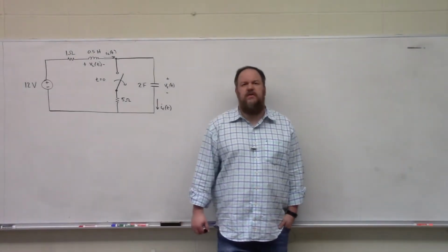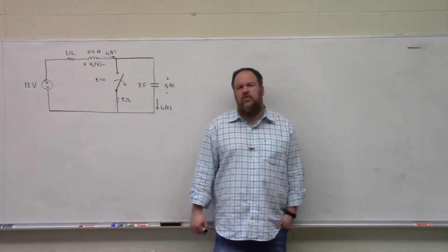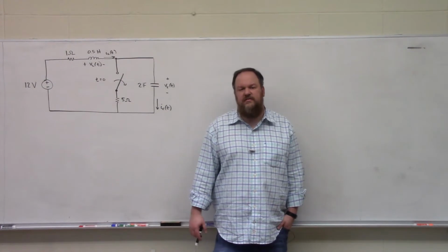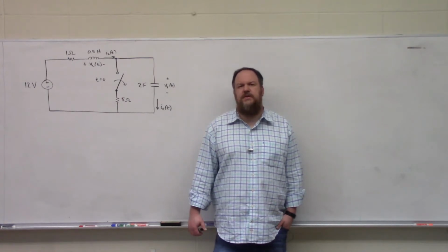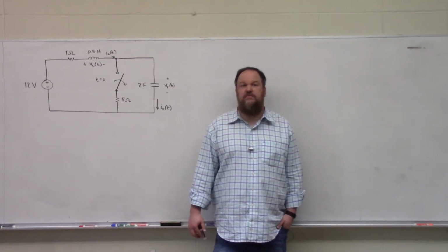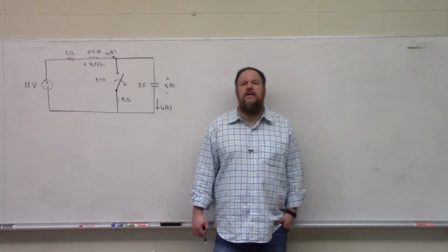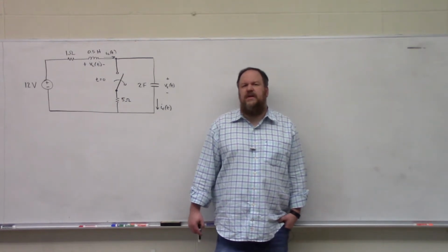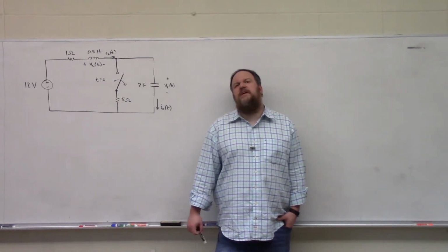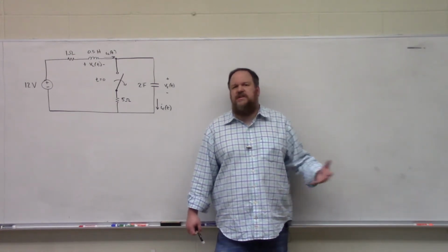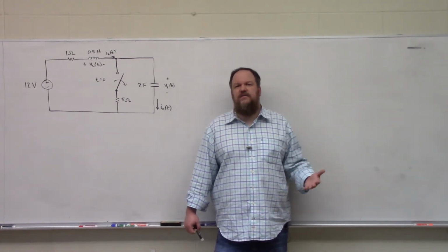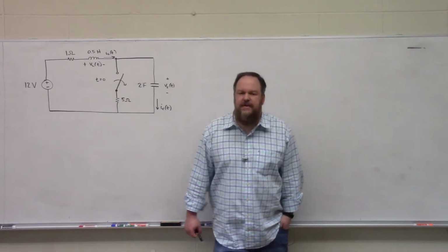Today we are going to be talking about solving for the total response of an RLC circuit. You may recall from circuits 1 that the total response of a circuit is the combination of the natural response, which we've already determined how to find, and the forced response. And the forced response was simply whatever the circuit parameter, be it the capacitor voltage, inductor current, etc., settled to at t is equal to infinity.